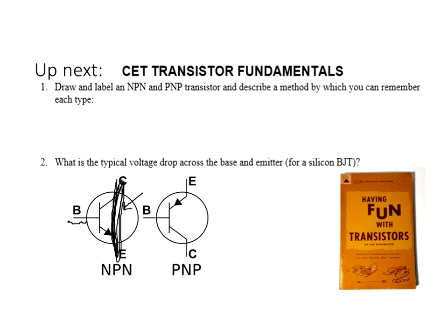By doing that, I can use it for switching or I can use it for amplification, but that is the basic purpose of a transistor, to control a ton of current in the collector and the emitter and use a tiny, tiny signal on the base to control a ton and ton of current. For example, over here in the collector and the emitter, I might be controlling 10 amps. And I can control that with a base with 1 milliamp. That would be a very, very good example. Tiny current controlling a lot of current.